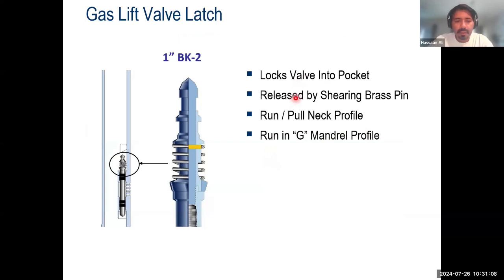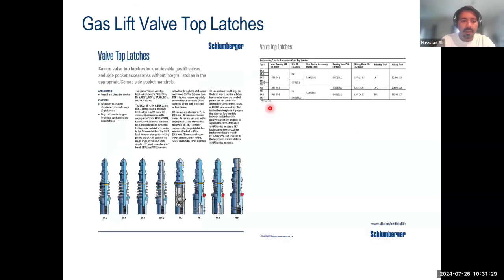There are a few design features of these latches. It locks the valve in place. It provides the running and pulling profile, and it ensures that the valve will remain in place throughout the life cycle of the well until an intervention tool will come and pull it. There are different types of latches for different types of applications.